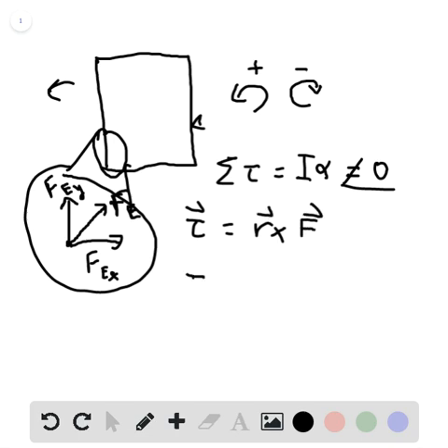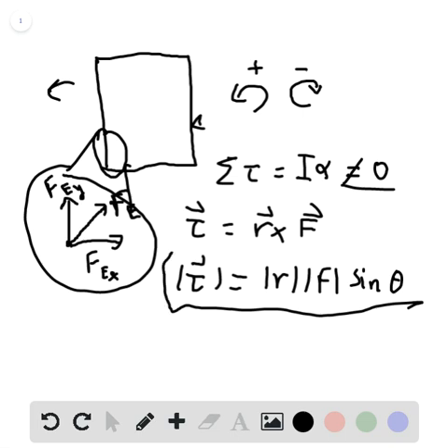But if we're just talking magnitudes, then this is the magnitude of the position times the magnitude of the force times the sine of the angle between them. In this problem, every angle between the force and the distances is 90 degrees. So sine of 90 is just 1, and we won't be dealing with sine. We're just going to have distances and forces.